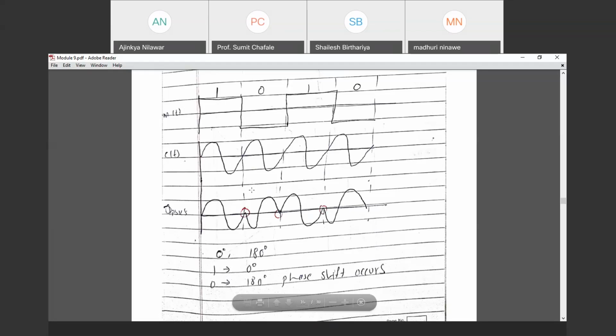You can take either; it is just a representation. Okay. So consider my input data 1010. Carrier signal, one cycle per sample. So what I am considering: whenever data 1 is there, the carrier wave as it is. But whenever data 0, 180-degree phase shift. 180-degree phase shift means a mirror image of this. Okay, I am not going into detailed phase and QPSK. You have already studied; it is not required as far as GATE is concerned. I am just representing this in pictorial form so you can understand where it will change.